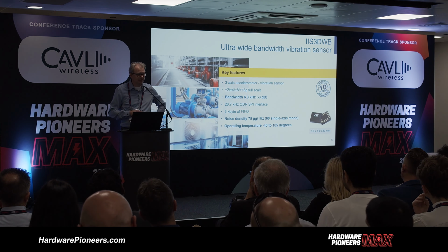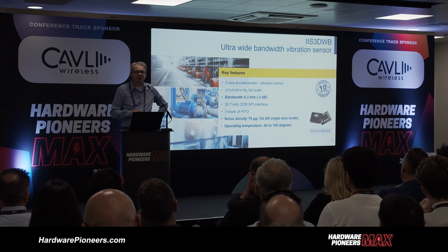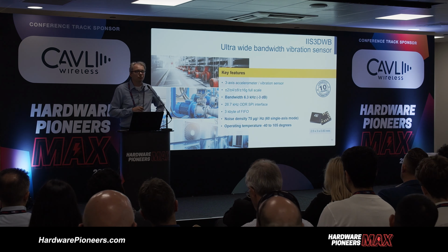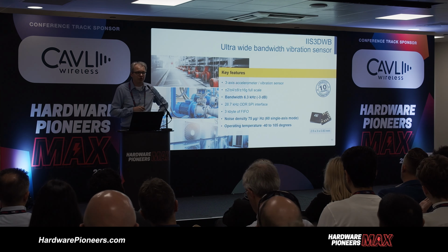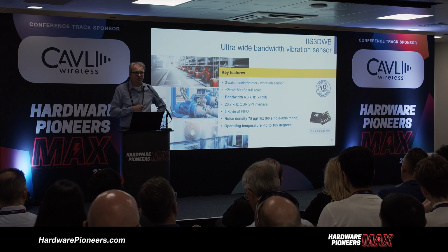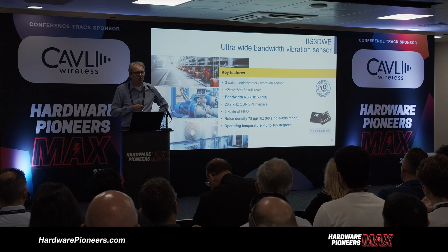The next example from the graph was the vibration. And here we have a very dedicated and actually brand new component. This is a roughly 2 year old acceleration sensor measuring vibration, so we call it a vibration sensor. The key merit of this one is that it goes up to 6.3 kilohertz of bandwidth. So from this perspective, it's perfect to monitor pumps, motors, and basically anything with rotating machines.